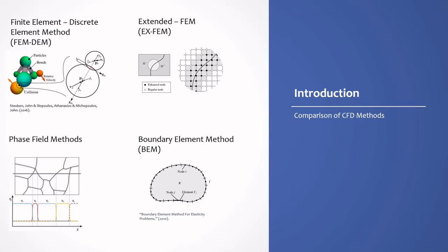Some of the newer, less conventional methods are finite element discrete element method, or FEM-DEM, extended finite element method, the X-FEM, phase field methods, and boundary element methods, BEM. Extended finite element method was developed to help solve problems with localized features, for example, the modeling of fractures. This does not require that the mesh be updated to track the path of the crack. The boundary element method, on the other hand, attempts to use a given boundary condition and fit those values into the integral equation. Then the integral equation is used to calculate the solution at any point in the interior. This method is specifically useful in simulating adhesive contacts.